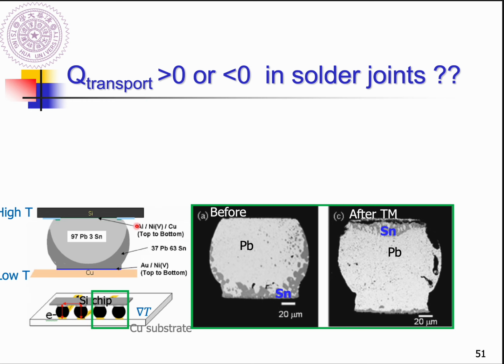So here, in the beginning of this section, we already showed that if your application is directly focused on the solder bond, we would suggest you add an additional solder bond nearby the solder bond which you are interested in, but without the current passing through.